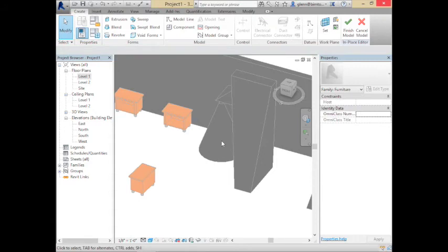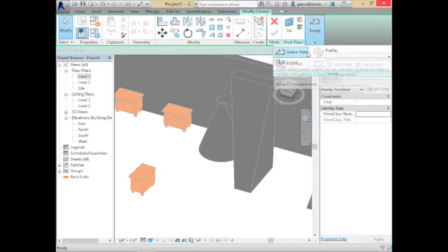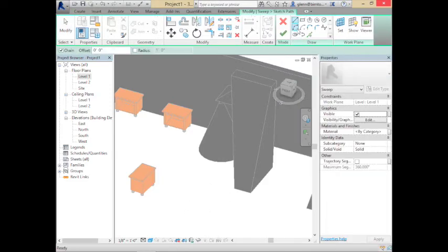So here's how it works. Sweeps have two pieces. Sweeps have a path and a profile. And what you often do is do the path first and then put the profile that you want dragged along the path. Okay, so we can do this a couple of different ways. I could go through and sketch a path. So for example, I could just put a path here on the floor. I'm just going to draw some arc.